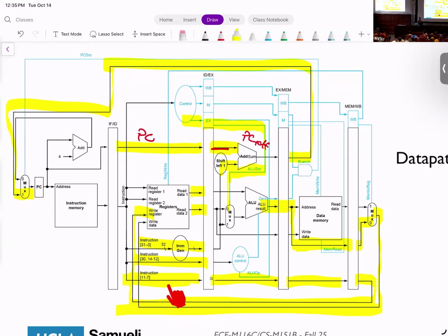When the instruction was in the decode stage, you create the control signal, you feed that control signal into the registers, and then you consume that control signal now here. So ALU source is now being read from the execution stage. It's no longer read directly from the controller because there is a different instruction here now, right? So it's kind of like you go back in time to use that information, right?